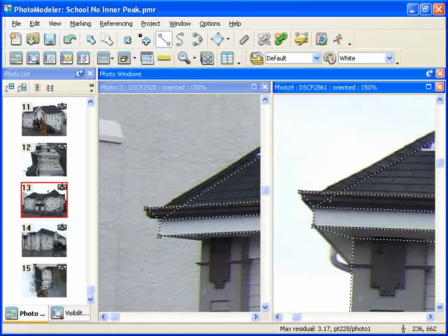If we had photos from above using a ladder or a neighboring building, we could mark and reference the tip of the roof. With only these ground photos, we could eyeball a point somewhere around here. But to mark obscured intersections more accurately, especially when obscured by something larger than this rain gutter, you can use temporary lines to indicate where the intersection is. If we create a temporary line extending the vertical edge here,